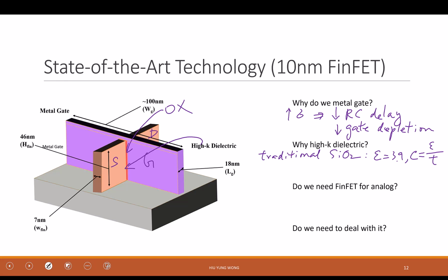Later you will see that, as we said, with the transistor we want to control the current or conductance in the channel. So we want to have a large capacitance. The larger capacitance can induce more electrons, so you reduce the resistance. But if we want to increase the current, then it means I need to keep reducing the thickness of the device, right? When you make it really thin, then you run into a problem called quantum tunneling.